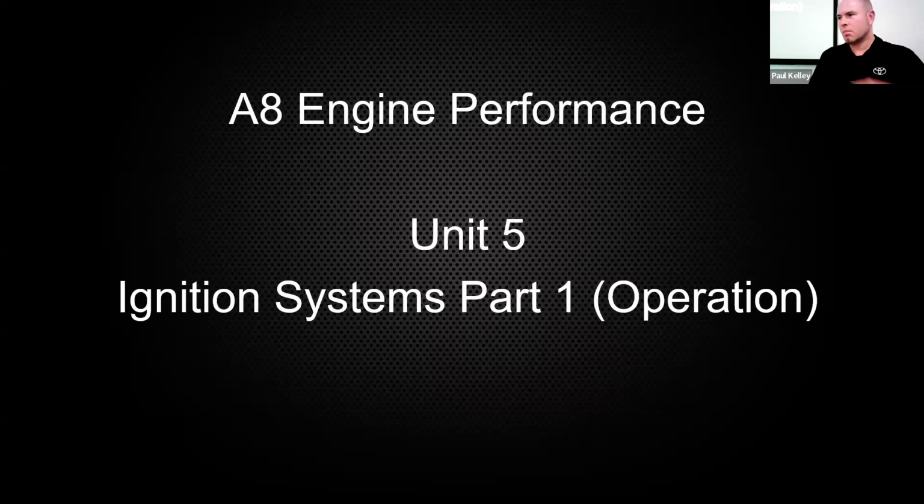All right, if you're ready, let's get the party started, shall we? So our unit 5 is going to be ignition systems, but this is part 1. Part 1 is going to be all about the system, the components, how the system works. There's a lot of different systems, so ignition's a really tough thing to cover. We could teach you all about coil on plug ignition systems and you'd be like, oh, that was easy, but then you pop the hood on something else and it'll be a waste spark or a distributor style or an older HEI style. There's like 1,000 types of ignition systems. So we got to go over quite a few of them.